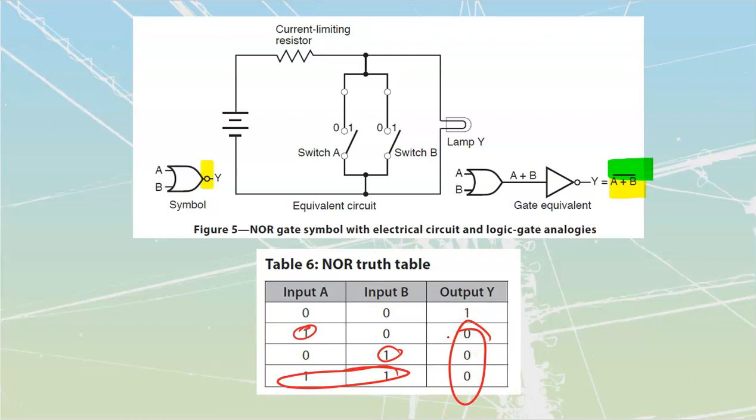I do want to note that this is also going to be the opposite of what an OR gate would be. A NOR gate gives us 1 and then zeros through all the rest of those. The OR gate gives us a 0 and then a 1, 1, 1. Like that is my output. Okay? It's just an inversion of that previous gate.